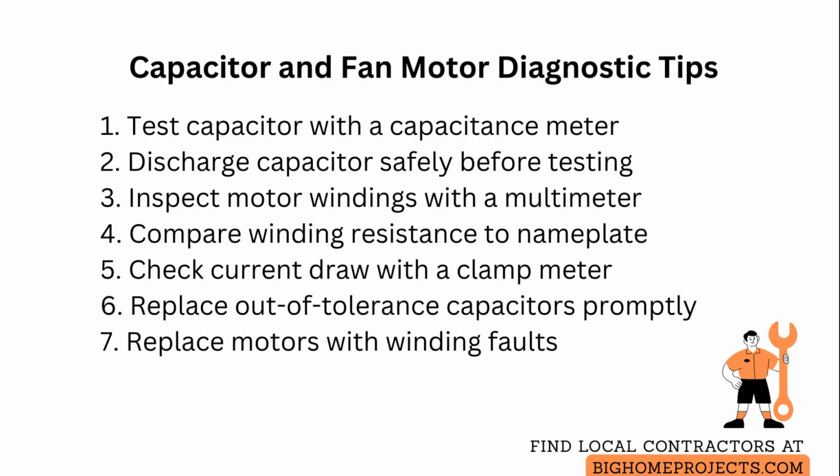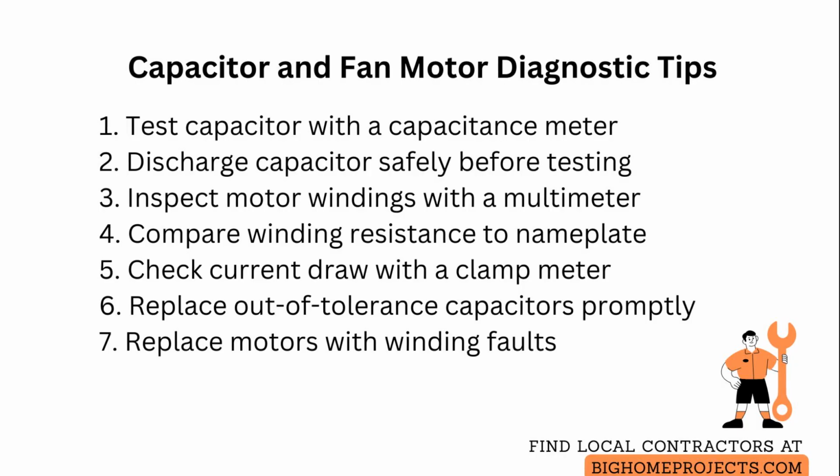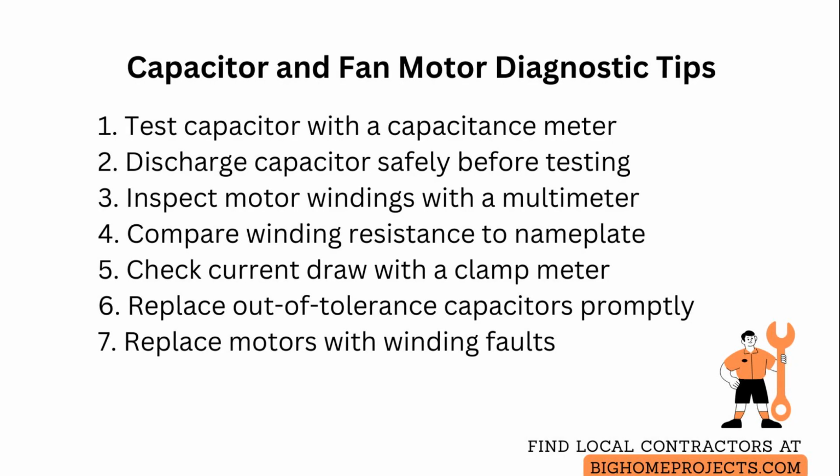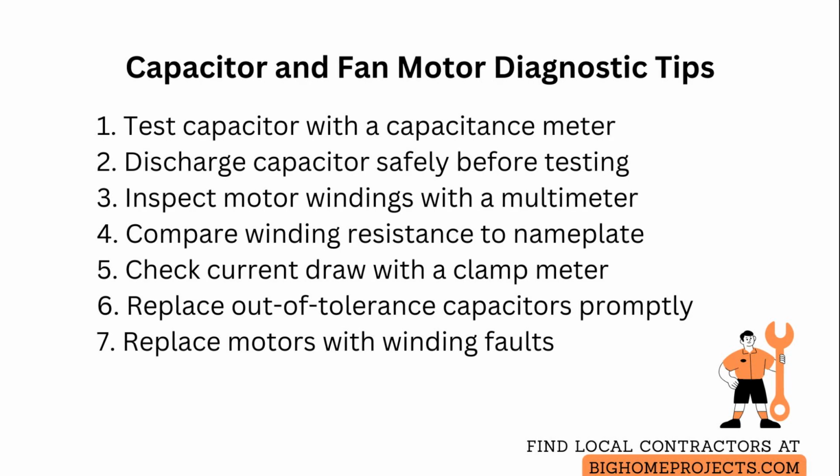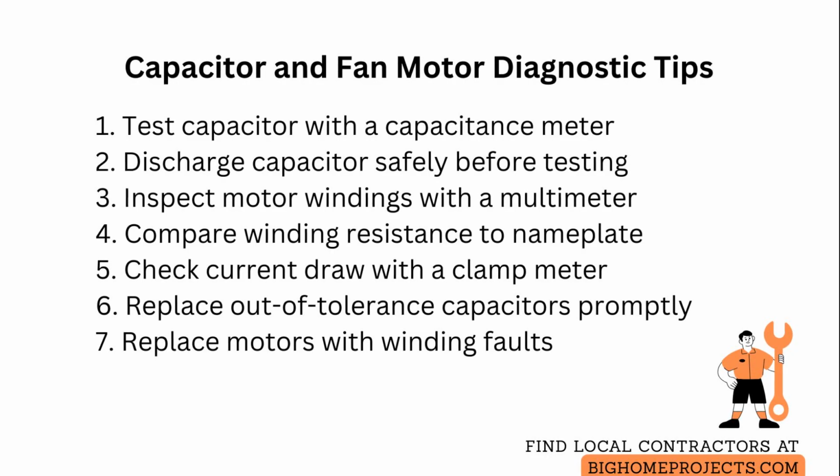Test the capacitor with a capacitance meter after discharging it safely with an insulated screwdriver against a resistor, or follow manufacturer guidance if unsure. Inspect motor windings for continuity and signs of shorting using a multimeter on the resistance setting, and compare readings to the motor nameplate when available.